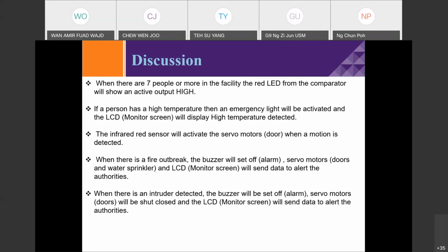And there's one flaw in our design, which is that in the event that on a particular day the total number of people that has entered the facility is more than 255, then the counter will not be able to function properly anymore, and the technical staff will have to manually reset the circuit by using the reset on the JK flip-flops. Okay, I think that's all from me. I'll now pass my mic to Junpo.